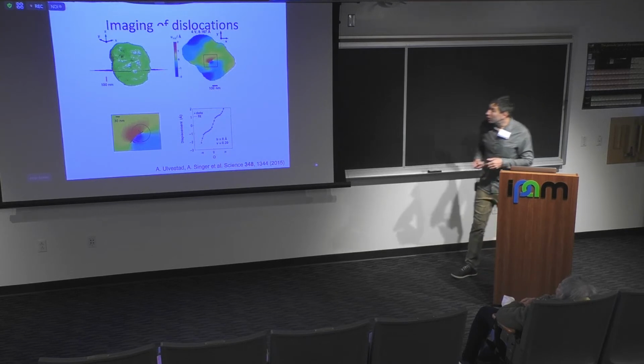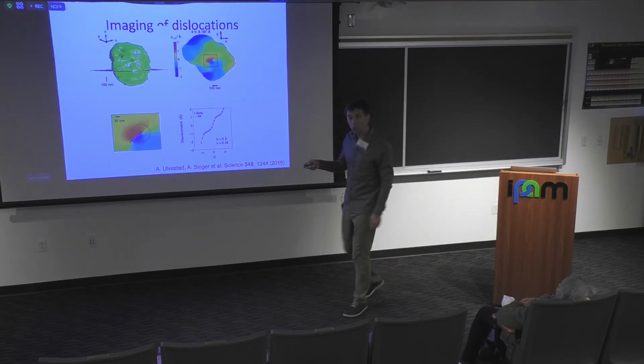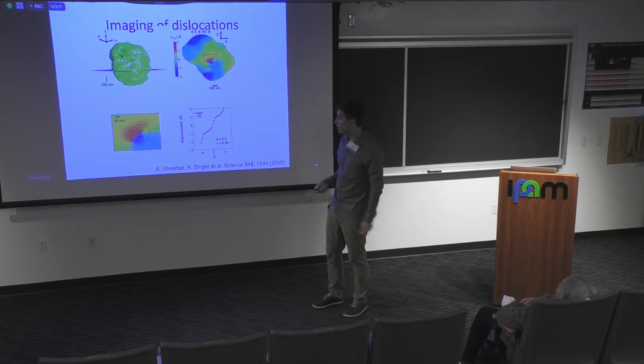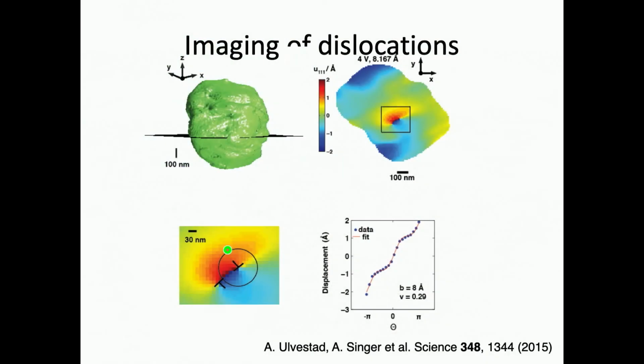The other cool thing, and we can prove, by the way, that this is a pair of dislocations, not only because it shows up as a dislocation in terms of the phase factor, but there is a really cool way that we can prove that it's not just any dislocation, but it's really an edge dislocation, not a screw dislocation, because we have a strain distribution around this point. And if we measure the strain distribution around this point, it's not uniform, it's not constant, which you would expect for a screw dislocation. It has some variation, and it fits exactly onto what the standard material science model would predict as a result of having this edge dislocation. And the only fitting parameters here are the Poisson ratio and the unit cell, which we already know, of course, because that's where the Bragg peak is found.